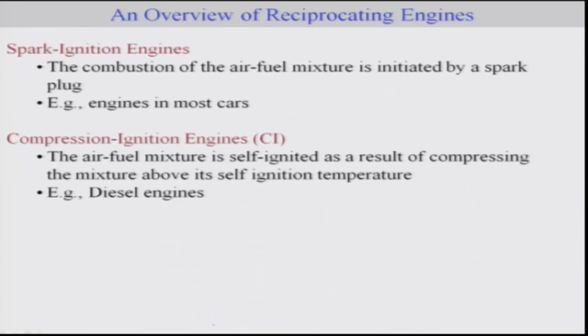Okay, as I already mentioned, you have internal combustion and external combustion. This is going to be internal combustion based analysis, where you can consider two forms of reciprocating engines. One is a spark ignition engine, where the combustion of air fuel mixture is initiated by a spark. These are basically the engines in most cars, the gasoline engine. The other one is a compression ignition engine, where the air fuel mixture is self ignited as a result of compressing the mixture above its self ignition temperature. This would be the case for the diesel engine. So we will first consider the spark ignition engines.